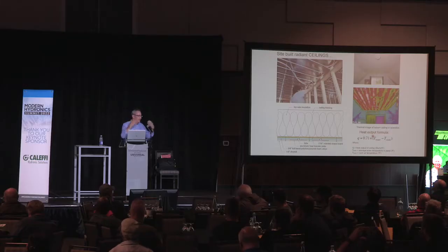The big thing is, of course, you can't run water or you can't run surfaces below dew point, otherwise you're going to get condensation. But radiant ceilings are ideal for chilled water cooling, provided you've got proper dew point control on the chilled water. They're better than a cold floor or a cool floor. So a radiant ceiling can do a really good job in heating. And, again, some clients think, well, how does the heat get down from the ceiling? Well, it's radiant heat. It's light. It's just like these lights on the ceiling. It shines down on objects.